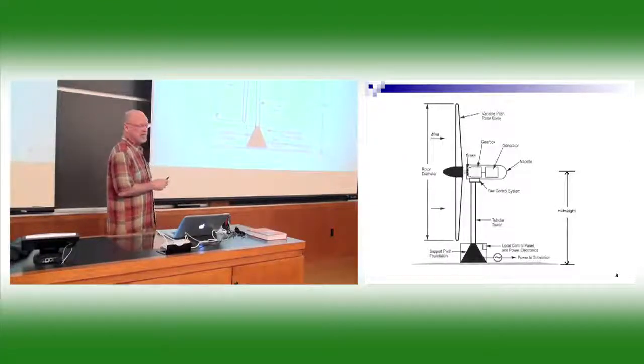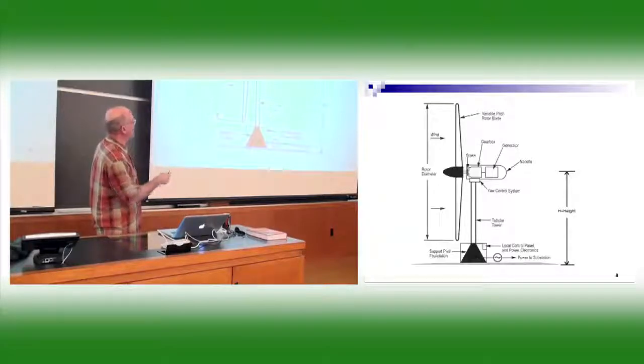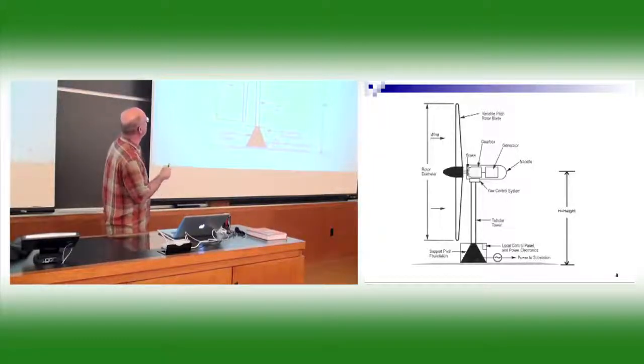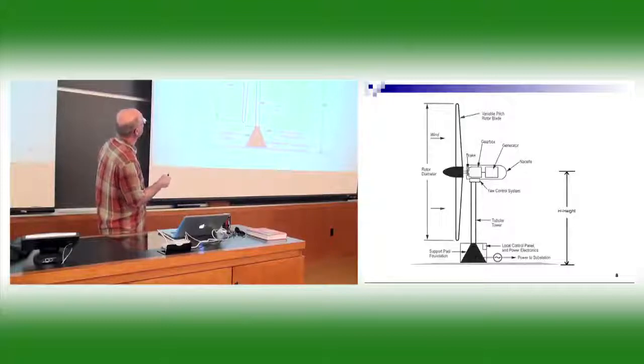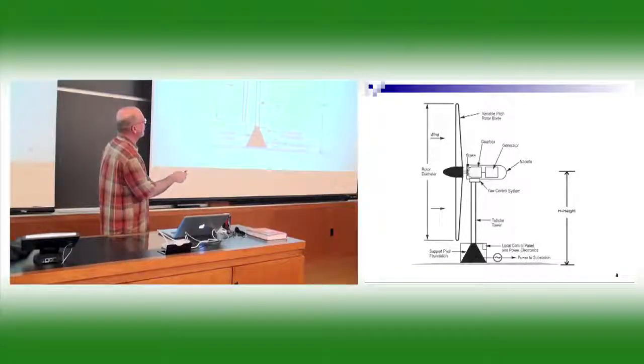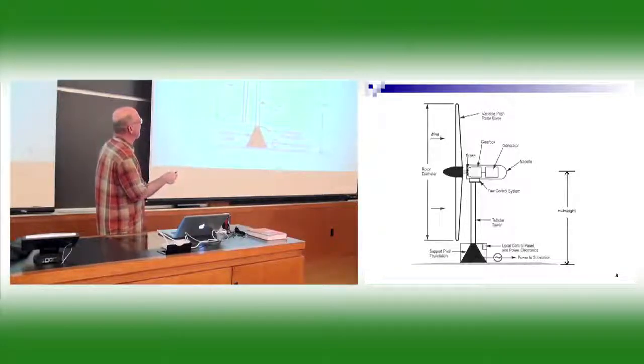Here's not just a schematic drawing, more of a real figure of what we're talking about with a wind turbine. You have, first of all, your rotor with these large wings, 2 or 3. The wind's coming from this direction. The height of this tower, of course, has to be bigger than half the rotor diameter, because the rotor has to be off the ground. Here you have your gearbox we talked about, your generator, and then it's covered with a nacelle. This is an aerodynamic fairing that keeps everything covered. You don't want a lot of wind drag on this because that puts more loads into the tower. You get plenty of lift from these blades to try to bend the tower.